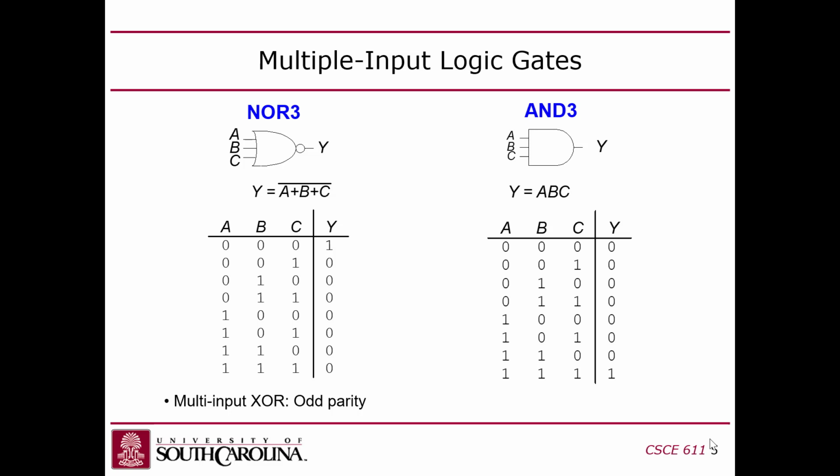So again, you can build these in a LUT on an FPGA, or if you build them on a custom chip, then you're building them with transistors. And in that case, there are some limitations on which gates you can build in CMOS logic. Okay, but not in a LUT. You can fill a LUT in with whatever you want.